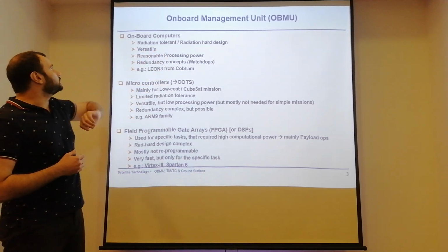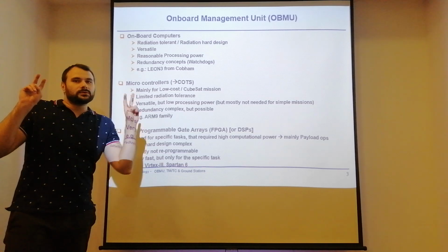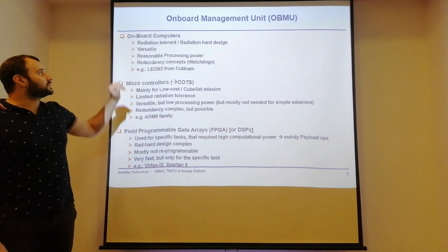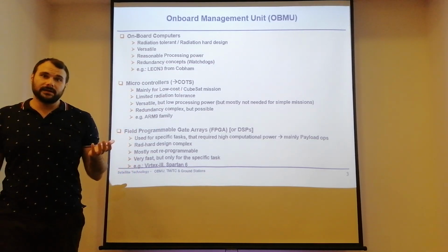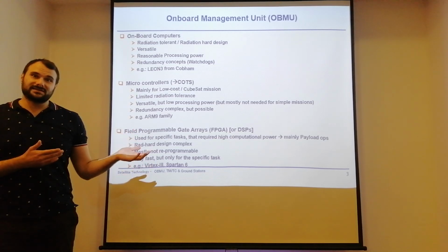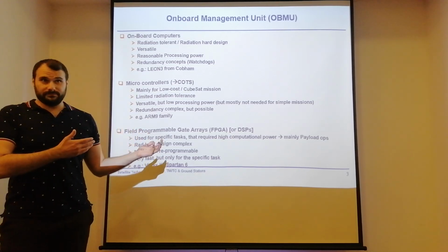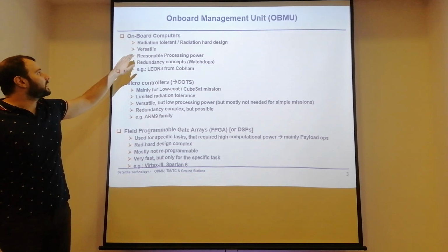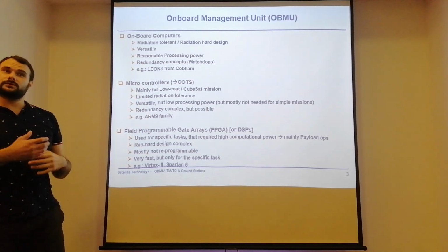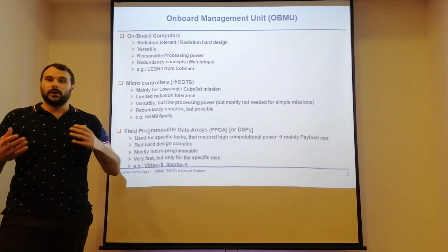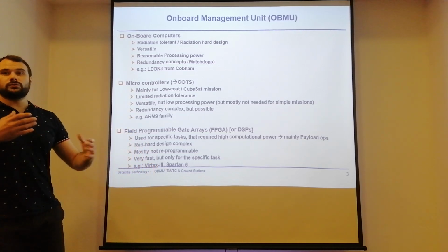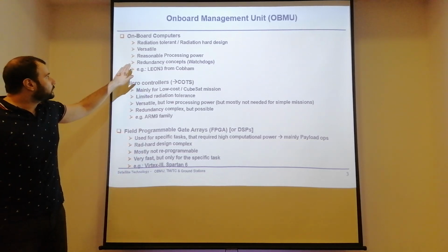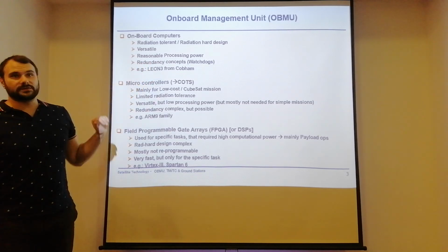So our onboard management unit, for instance, could be comparable to an ordinary PC, to a computer. And those onboard computers are usually radiation tolerant, or at least radiation hard by design, because as we all know, the environment in space is not really favorable for our computer. The main advantage of those onboard computers is that they are really versatile. They can be used for many different tasks to operate, to control, to measure, and you're not really limited to a specific function. And another advantage is that they offer a reasonable processing power as well.